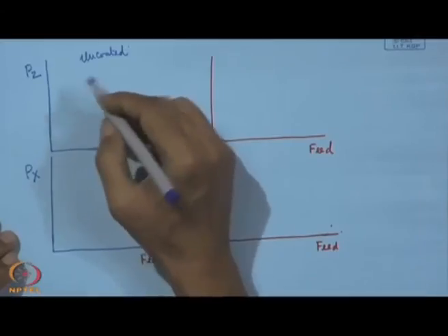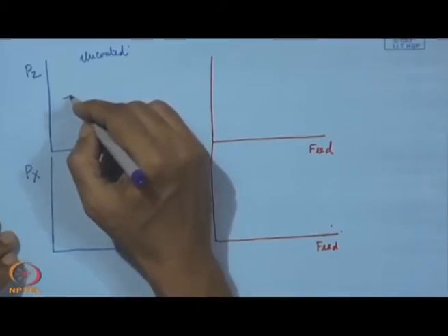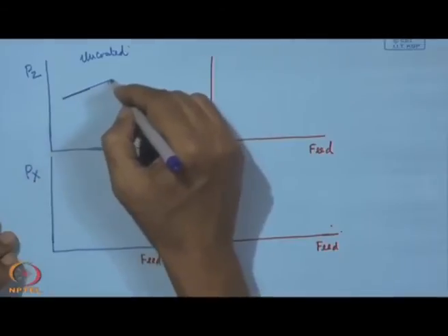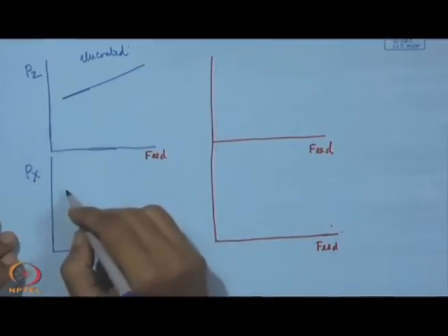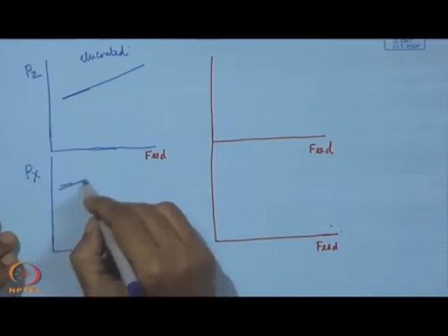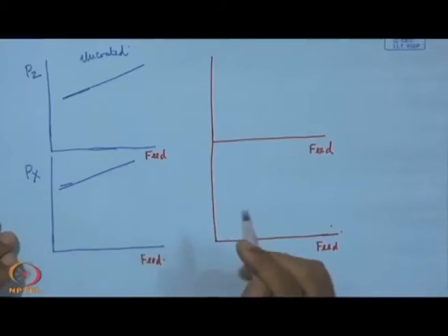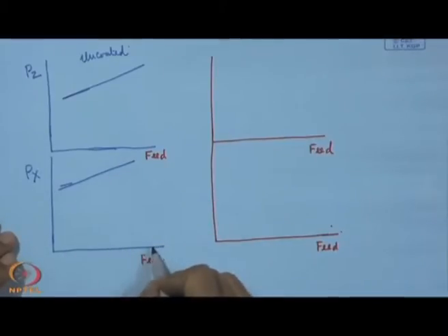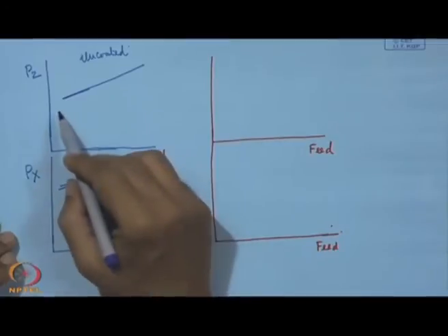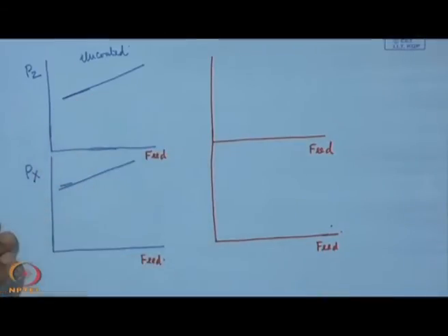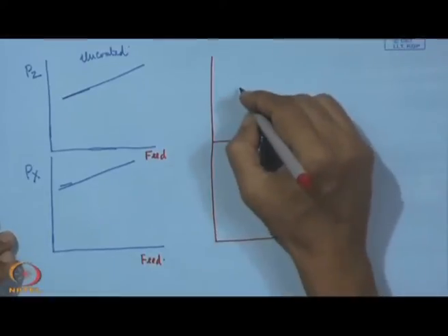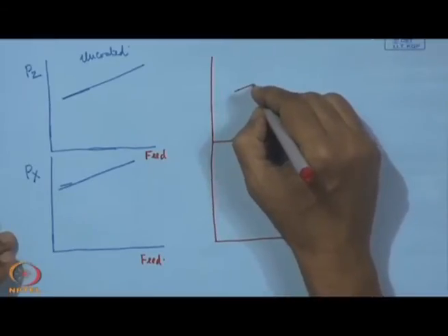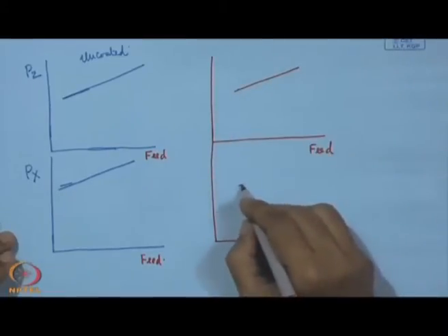That means, if we say this is the curve for HSS, so we draw these two curves. Here we increase the feed with the same speed and we see that these are rising, and when it is drawn for the coated tool, we have to see where is the location of this one and where is the location of this one.